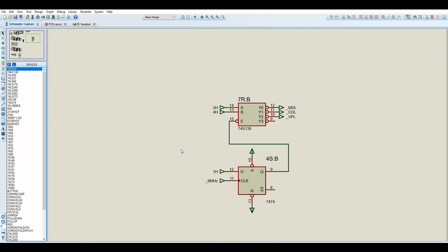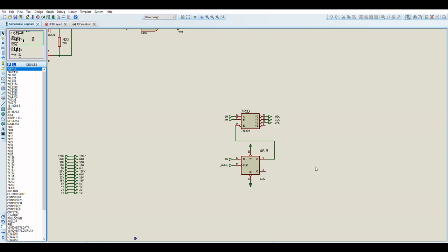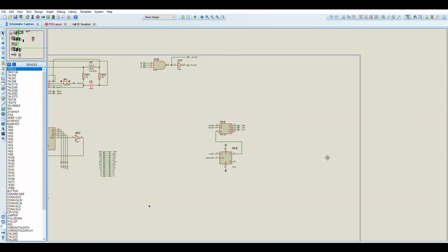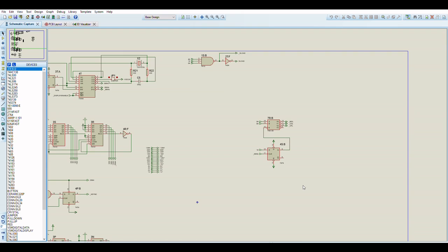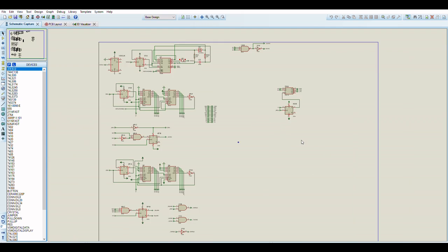And this is all based on the pixel horizontal position, but also based on a nice clocked input as well from this, just to make sure that all of the internal pixel signals are synced properly. Because there are various ways in which sometimes the sprite registers, for example, or the character registers, or the character screen, and the output pixels for the characters and the tiles are delayed by 1 or 2 pixels.